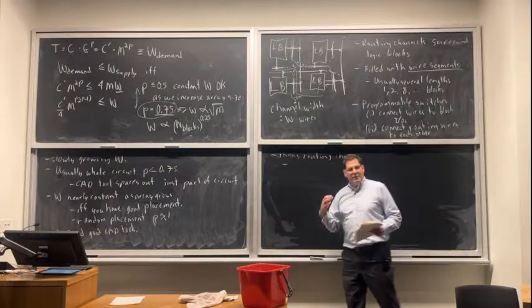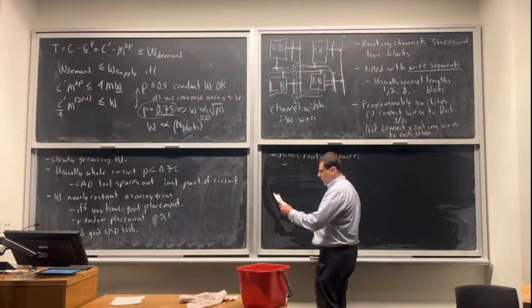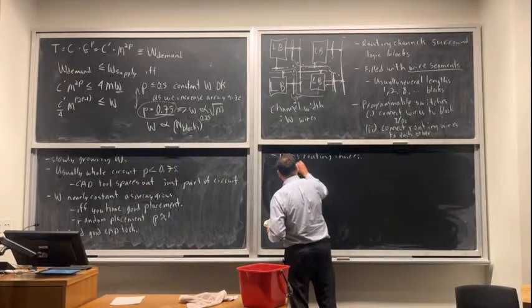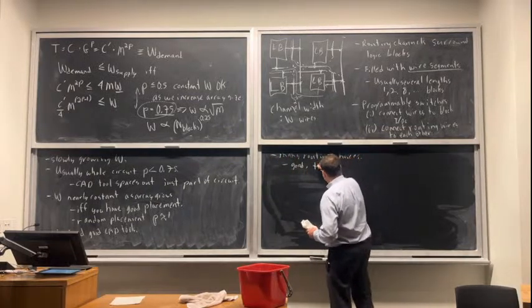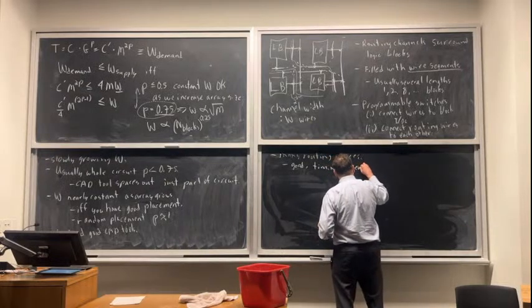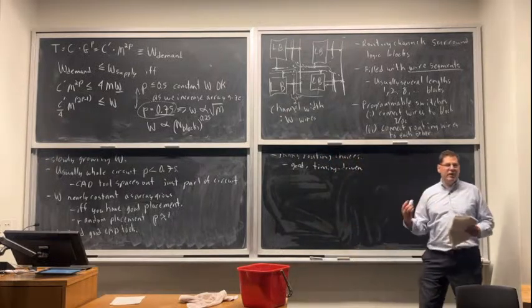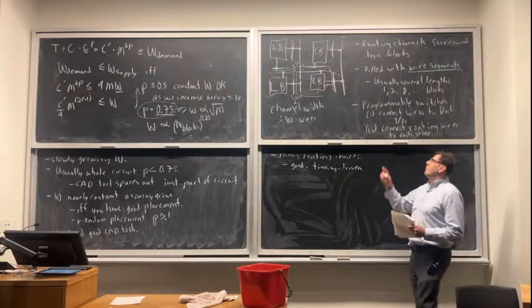So that's kind of a strength of you have lots of options, but you need a CAD tool that can explore those all quickly. So you need a good router, and it has to be timing driven. Timing driven means it figures out what are the speed limiting paths of your circuit, and it gets them fast routing.